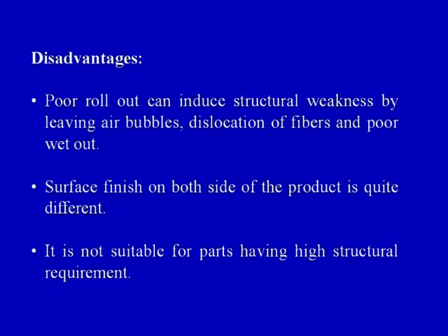It is not suitable for parts having high structural requirements, because the load bearing capacity of the discontinuously reinforced polymer composites is relatively low as compared to the continuously reinforced polymer composites. So in this particular case we can see, as the spray gun is being used, from the spray gun we are getting chopped fibers and a polymer.